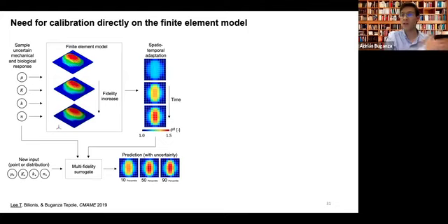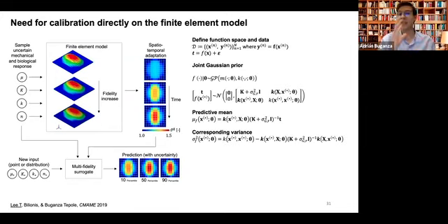So we have used an ODE model in the past, and what if we want to use experimental data? So we want a framework that can take different types of models. And this is usually a multi-fidelity scheme. So for this particular case, I only changed the coarseness of the mesh, but other possibilities are available. And again, you have to sample pairs of input outputs in order to build this surrogate. And in principle, it looks very similar to the Gaussian process that I was showing before.